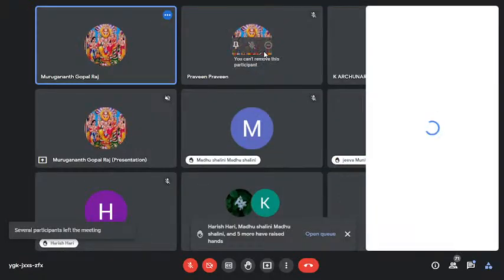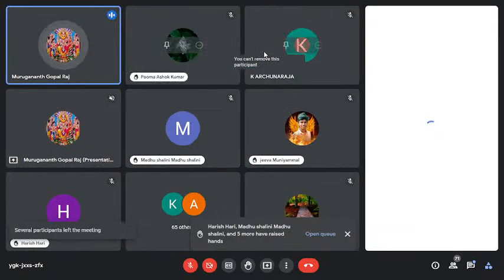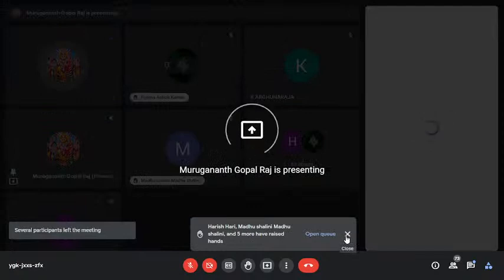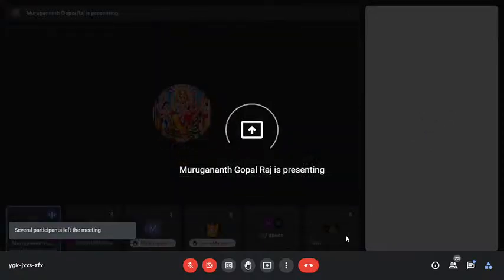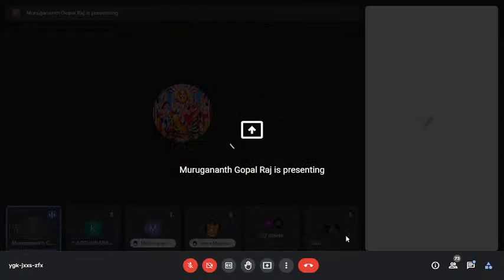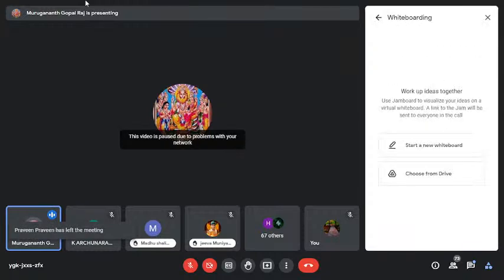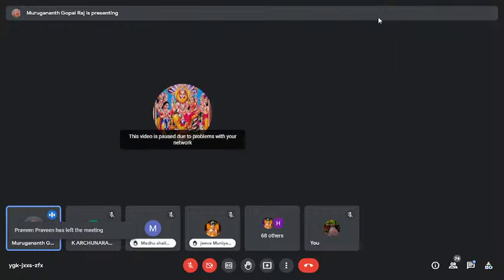So these are the steps involved in the preliminary energy audit. First one is planning and organizing, then conducting a walkthrough, collecting the macro data, analysis of data collected, and recommendations for further improvement. So these are the base steps involved in the energy audit, right? So we have discussed this energy audit at length, and these are the instruments that are used during the audit. But now let us come to the most important point, which is the topic of today, that is energy conservation and do's and don'ts in the home energy sector.